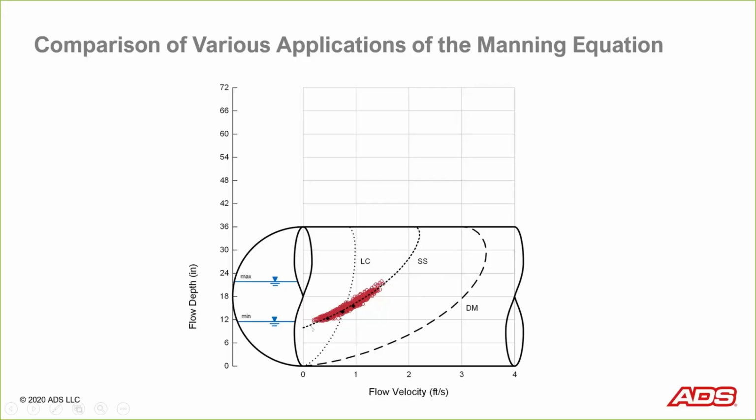So in this case, whatever condition is present in this pipe is causing us to lose about 1/3 of the capacity of this pipe. Turns out we had a field crew that went out to investigate this site, and it turns out that there was, I believe, some type of concrete or something like that that was built up in one of the downstream manholes. Once that was chipped away and removed, flow conditions returned to normal. And more importantly, the implication of that is that we reestablished the capacity of that pipe. So this is a good illustration here of the difference in these three methods, particularly when you have something like a non-uniform backwater type condition, which is actually not all that uncommon in sewers.